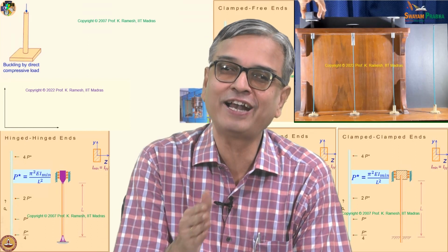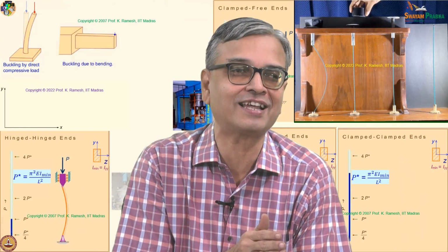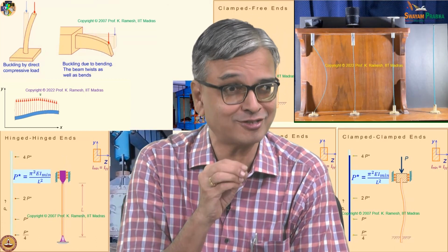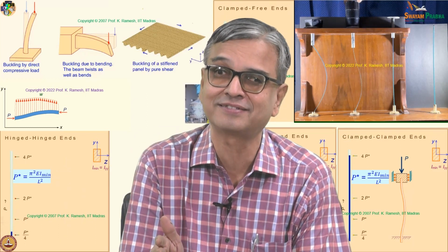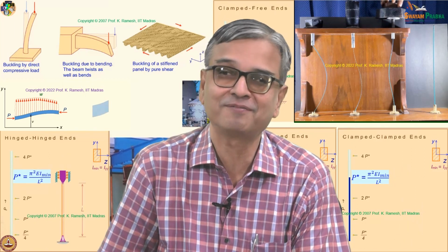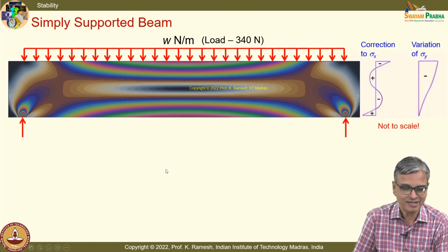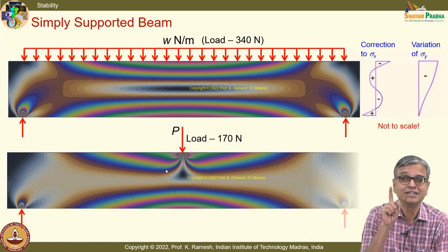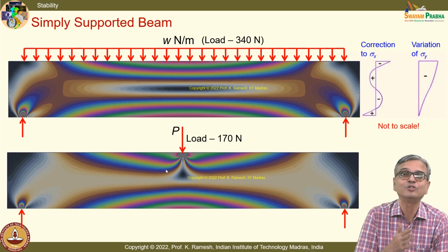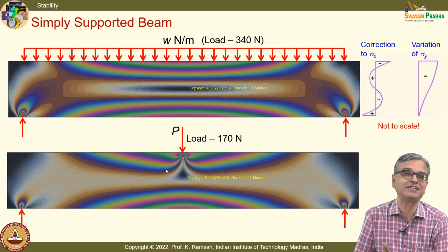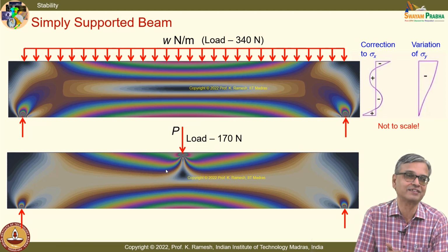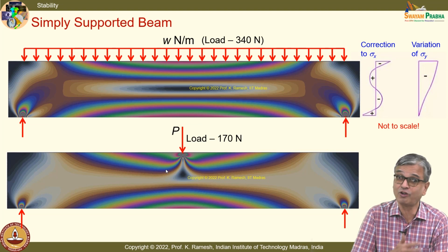Whenever you find deviation between experiment and your mathematical analysis, one of the blame is on the equipment, not on the performer. The performer has to be careful and systematic in performing the experiment. These are the usual ways people wriggle out of real challenges. And I have said only in buckling experiments, even when you do a careful experiment, the deviations are very high because you cannot get a perfect material. You cannot have a perfect cylinder. You can't have a perfect sphere free of defects. So, they are all very, very expensive.